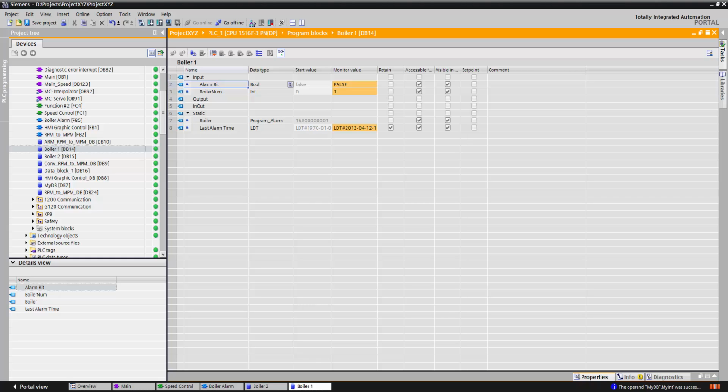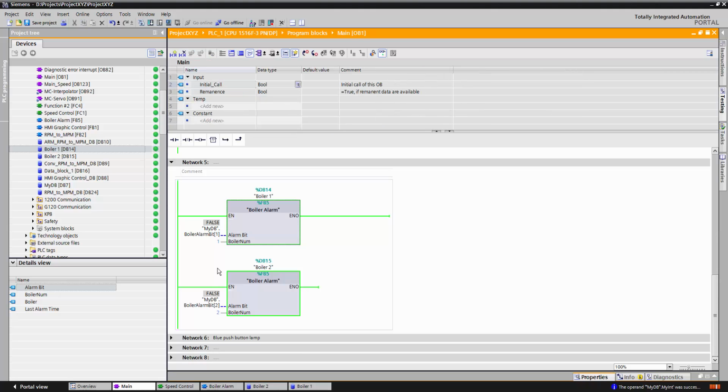If you're running a machine that is actively having forces on it, well, you're running the machine in a way that it was not designed to be run. So, if you do have to resort to forcing an input or an output, make sure you have a plan in place to fix the underlying problem.